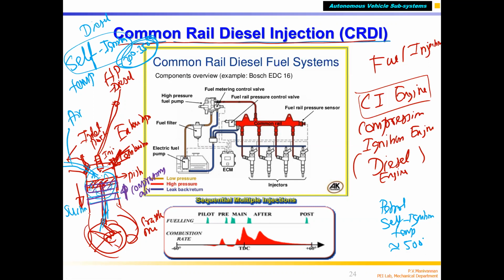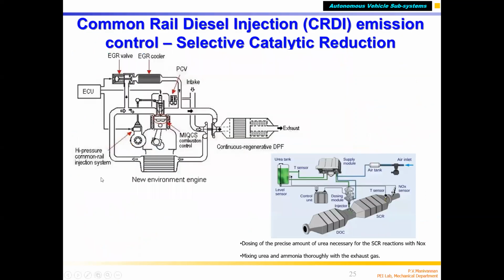So then what you do, you inject the fuel. Diesel fuel is injected, sprayed at very high pressure, correct. In diesel, fuel injection, generally in the old generation, I'm talking about the old generation diesel engine, 20-30 years before, the injection pressure was 300 to 400 bar, or 200 to 350 bar something, correct. 400 bar pressure, correct. So you are spraying the fuel at 300 bar.